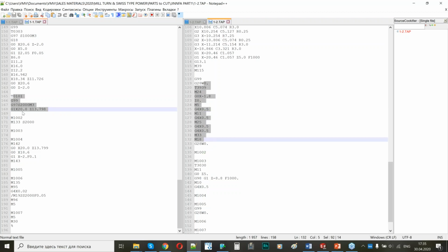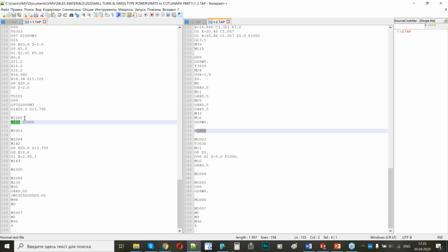During the ejection cycle, the machine is calling my cutoff tool, positioning the stock, positioning the tool. I have my synchronization mode separately. There is a special M command to synchronize the spindles of this machine. It's a more complex process and will not be easy to write manually, because we need to perform a nice synchronization. The second spindle is waiting while I turn on the synchronization on the main spindle.